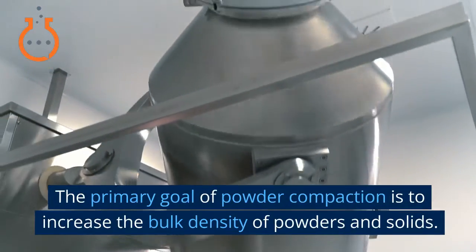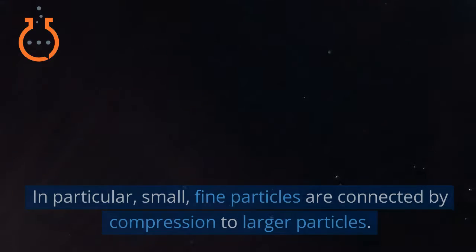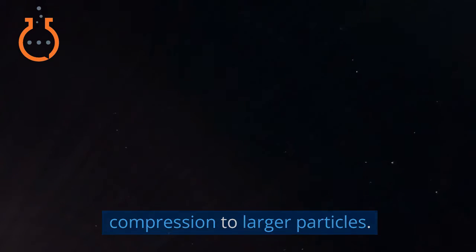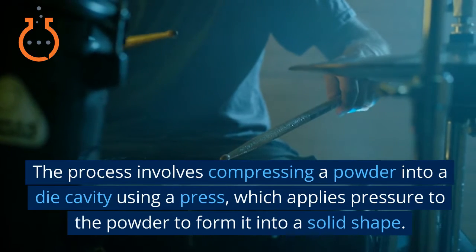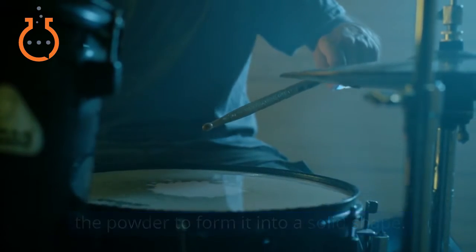The primary goal of powder compaction is to increase the bulk density of powders and solids. In particular, small, fine particles are connected by compression to larger particles. The process involves compressing a powder into a die cavity using a press, which applies pressure to the powder to form it into a solid shape.